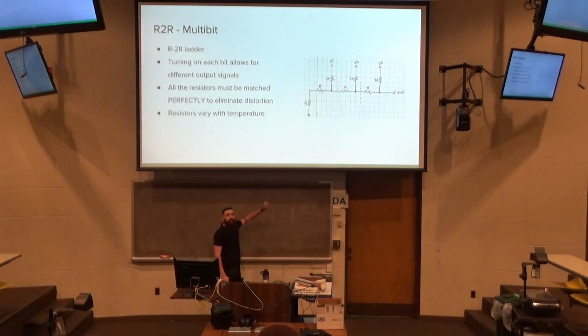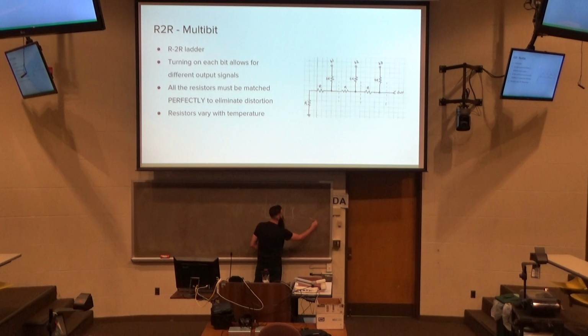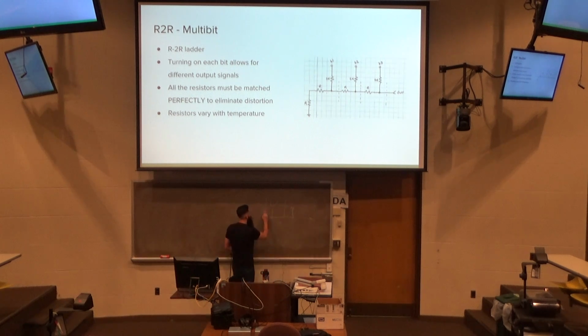And instantaneously, we're just talking about one frame of our sampling rate here. Sorry to the people who are online who can't see me right now. But we'll go outwards like this, and there's resistors in here and in between that will actually compound to make this bit worth less compared to this bit as far as the voltage added to the output signal. Does this make sense? So we'll apply instantaneously, not talking about changing these at all yet. We'll apply 1, 0, 1, 0.